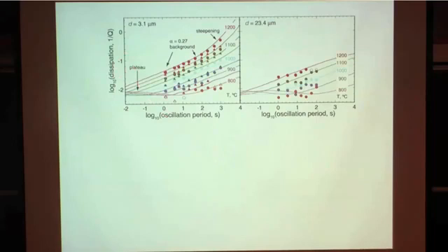If we look then at dissipation, this is where we're getting to what Miyake was talking about yesterday, the absorption band. If you look at dissipation, exactly the same, so oscillation period versus energy loss, you can see, again, temperature, the energy loss is the least at the lowest temperatures. So at some point, if we have perfectly elastic behavior, right, there's no energy loss. As we increase in temperature, we get more and more energy loss.